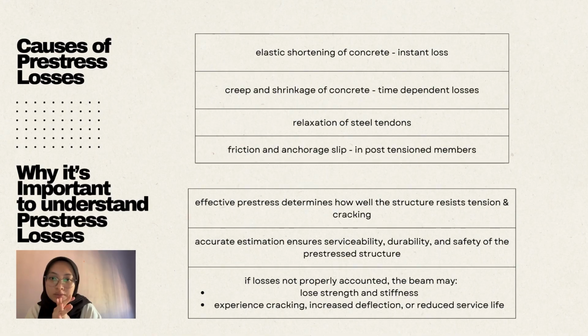Next, why is it important to understand pre-stress losses? It is because the effective pre-stress determines how well the structure resists tension and cracking. Accurate estimation also ensures the serviceability, durability, and safety of the pre-stressed structure. If the losses are not properly accounted for, the beam may lose strength and stiffness, and it will also experience cracking and increased deflection or reduced service life.